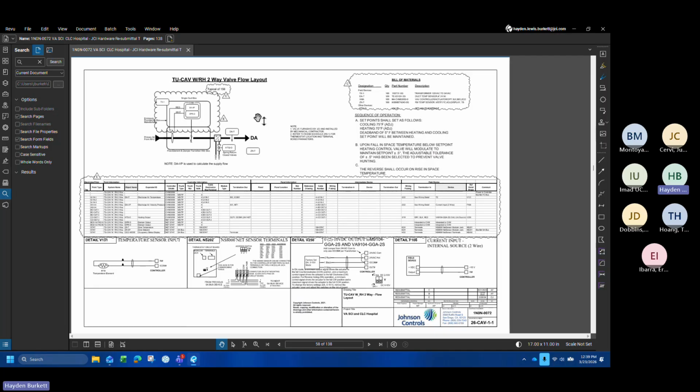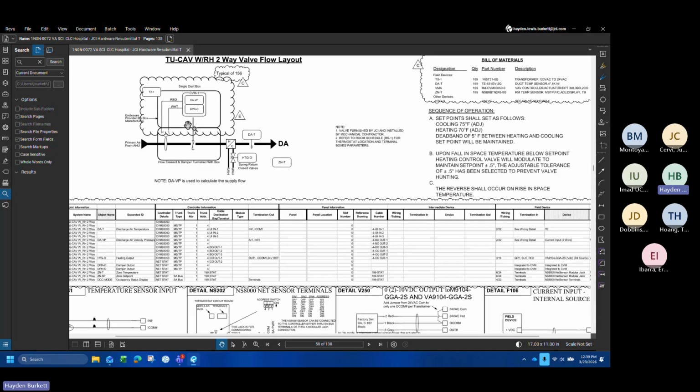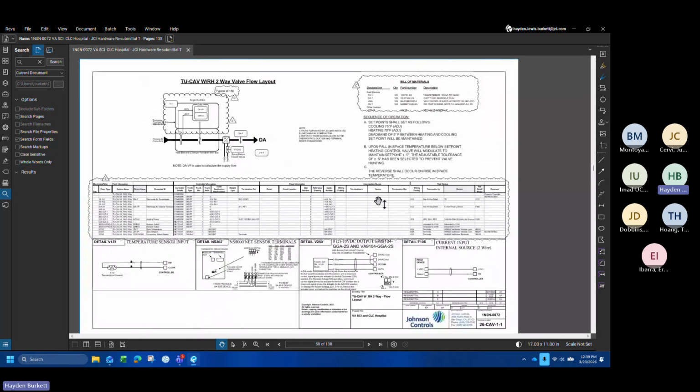Now we get into terminal units. These systems have very few points associated with them, and that's why there's a lot of information on the screen. It kind of gets me laughing a little bit looking at all this information. Internally, these VAV controllers utilize discharge air velocity pressure to determine CFM. It uses two pressure reference points to determine that. We've got our zone temperature, our discharge air temperature, and our heating output.